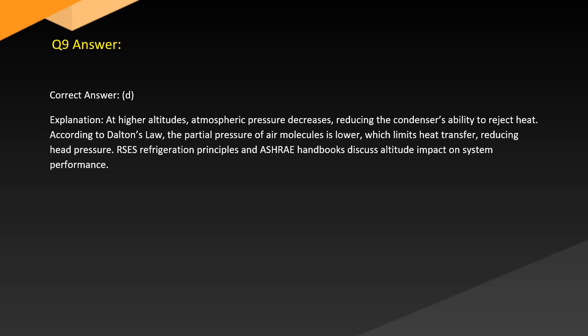Answer. Correct answer: D. Explanation. At higher altitudes, atmospheric pressure decreases, reducing the condenser's ability to reject heat. According to Dalton's law, the partial pressure of air molecules is lower, which limits heat transfer, reducing head pressure. RSES refrigeration principles and ASHRAE handbooks discuss altitude impact on system performance.